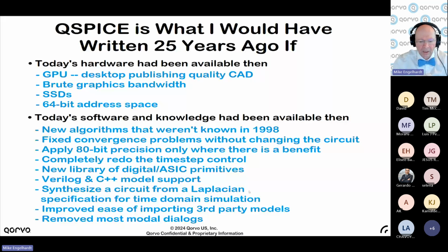So you'd like an FFT that lets you have frequency bins that are spaced exponentially, so that each bin further out is a bigger swath of frequency, and no such routine exists. All you can do is try to pick the decades of interest, and then maybe do an FFT of 1,000,000 points, capture 6 of those decades and do the Fourier transform of that.